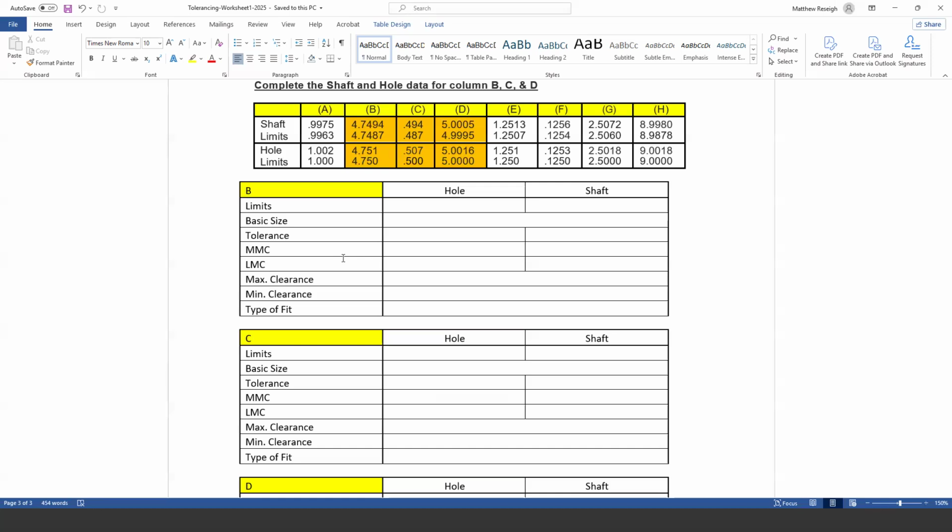Or they can chill something down really cold and shrink the material way down and then slip something over it that's maybe been heated up. So you actually create the clearance you need to make the parts fit together. Then as they go back to room temperature, they have an interference fit. They're locked together. So things can be designed to look like they won't fit together, but with heating and cooling, we can force them to fit together.